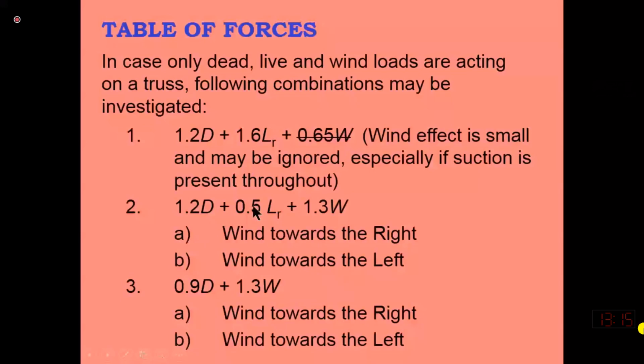So this is the combination that we might use, for example, in winter, but in summer or maybe when very high wind is blowing, the effect of the live load will be lesser. So we have to consider the possibility of all types of load which may occur. The maximum magnitude of all the loads cannot occur at the same time. You might ask why we are not considering this 1.6. If we consider it as 1.6, then this is an unrealistic case.